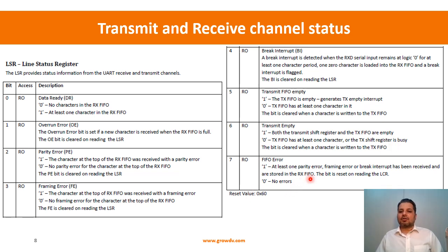And then you have the FIFO error. It says at least one parity error, framing error, or break interrupt has been received and stored in the RX FIFO, and this bit is reset on reading the LSR, right? So this is the specification. Whatever specification has been given, we need to adhere to it and implement the testbench functionality.